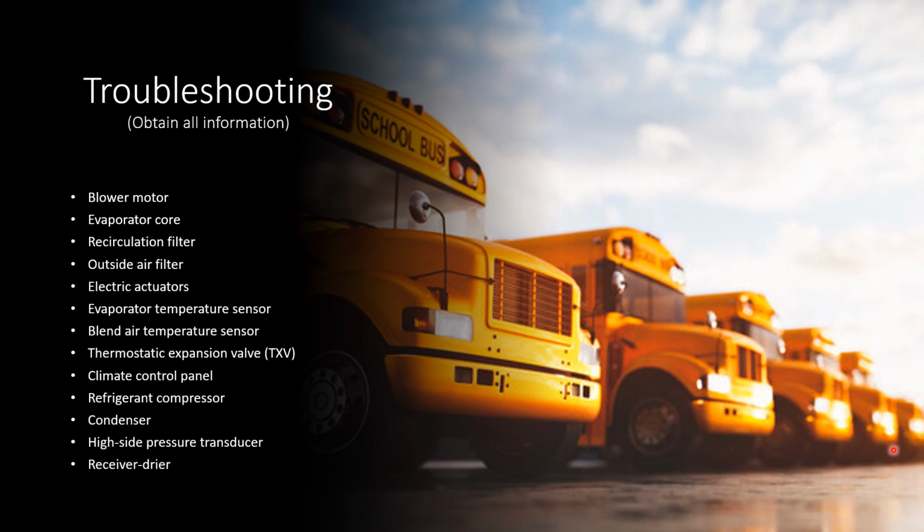Now, another very important thing you need to know is if there's a logic ladder, which means that there are rules of engagement. So if the computer doesn't see a good temperature sensor, then it's not going to allow the clutch on the compressor to come on. So you have to understand if there's anything of that sort that's going to prevent you from furthering your diagnosis.